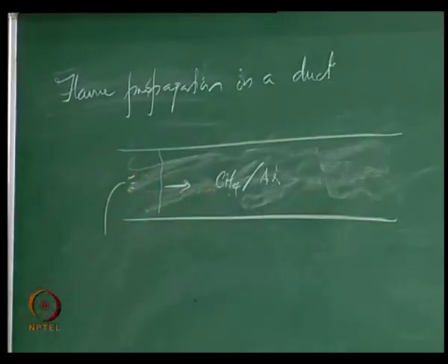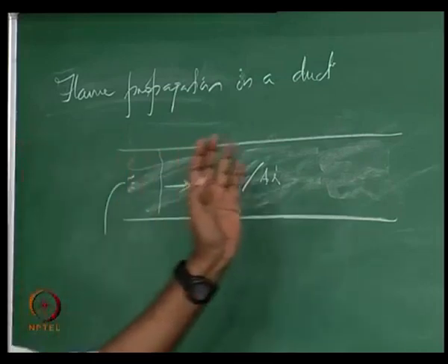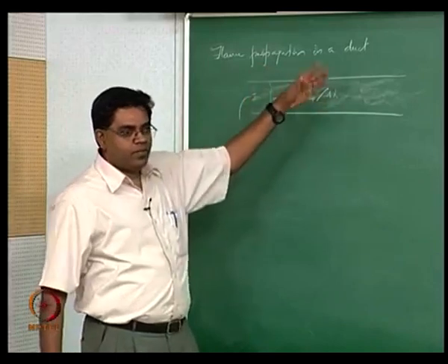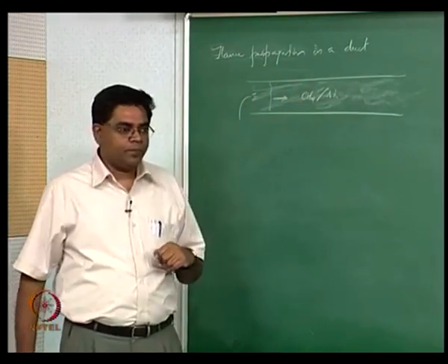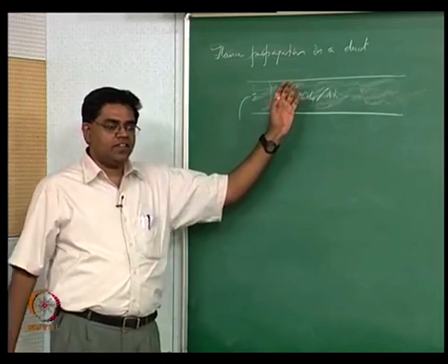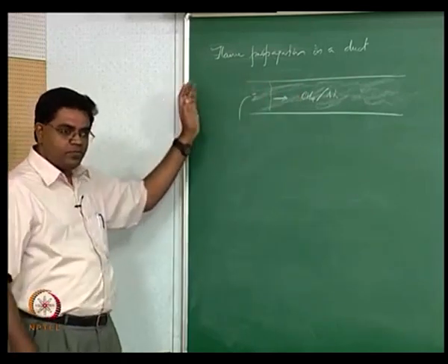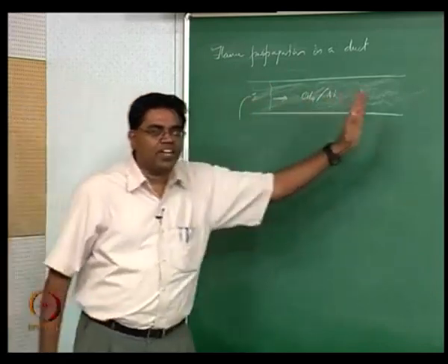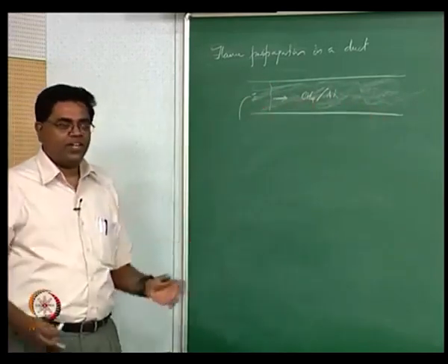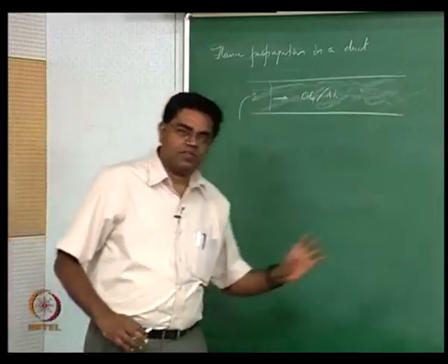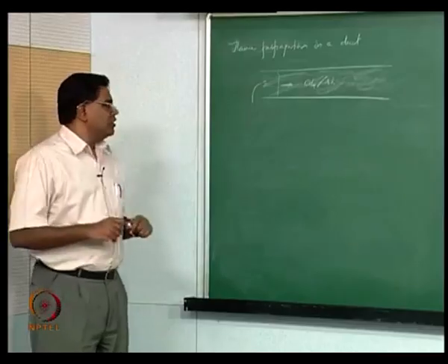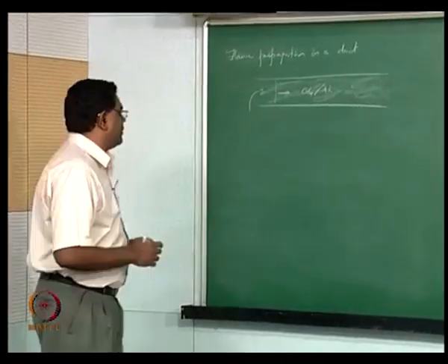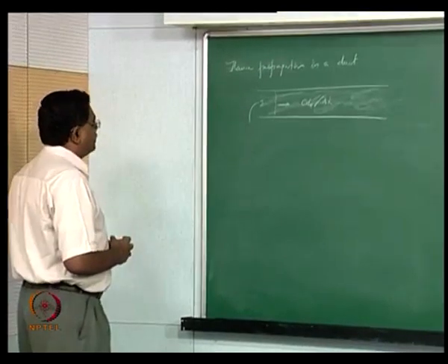Now of course there are lots of nice interesting studies about flame propagation in tubes that are progressively of smaller dimensions, and then you will find how the flame convolutes and so on, right. And you see that the gases behind have to flow away from the flame for a deflagration, and then they begin to actually have a velocity profile as the flame propagates and all those things, okay. But that's because of the no slip boundary condition. So we'll now talk about flame propagation in a duct rather than being stabilized on the rim outside a duct that is vertical.